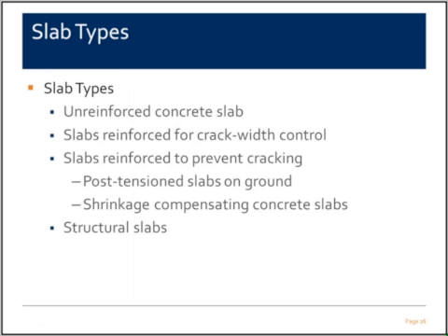We can conveniently subdivide slabs into different types, and these bullet points follow the ACI 360 categorizations. The slabs can be unreinforced concrete slabs, the plain slab, for example, sidewalks. Most light-duty warehouses like your typical Targets and Walmarts and so on, are built out of unreinforced concrete slabs. It has certain capabilities, but the most important thing is jointing in this type of slab.